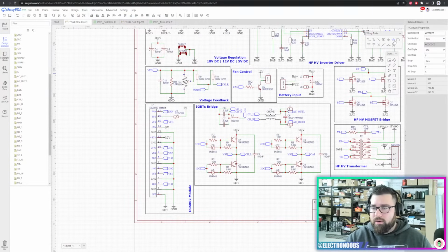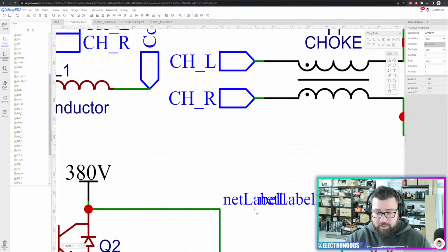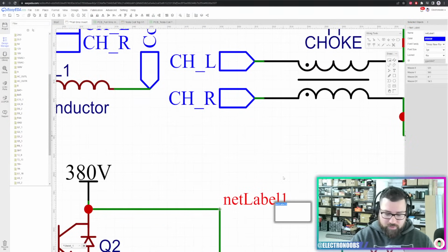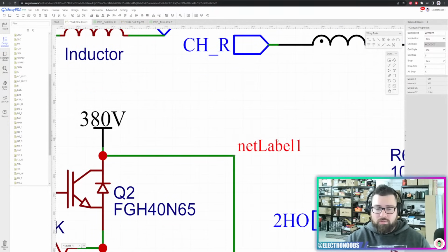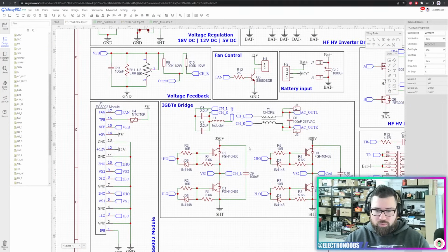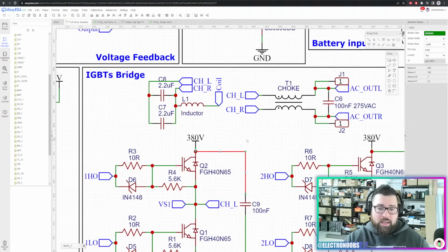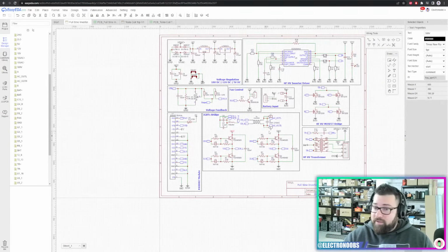Obviously we have more symbols here. We can use this one if you want. You can also change the name to this one. I think this one is for giving a net label, so you just place it on the net and then you just change the name of that, let's just call it IO, and then this entire net will be called IO. I'm not really recommending this because I want to leave the software to give the name to the net however it wants, and I only want to change the name of the connection. So, everything understood till now?